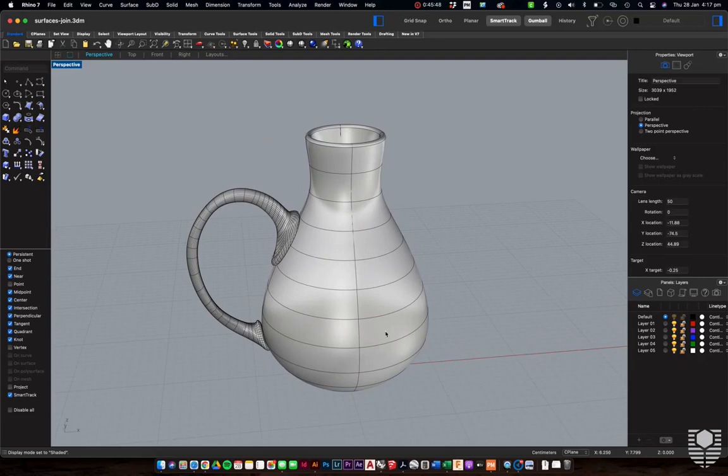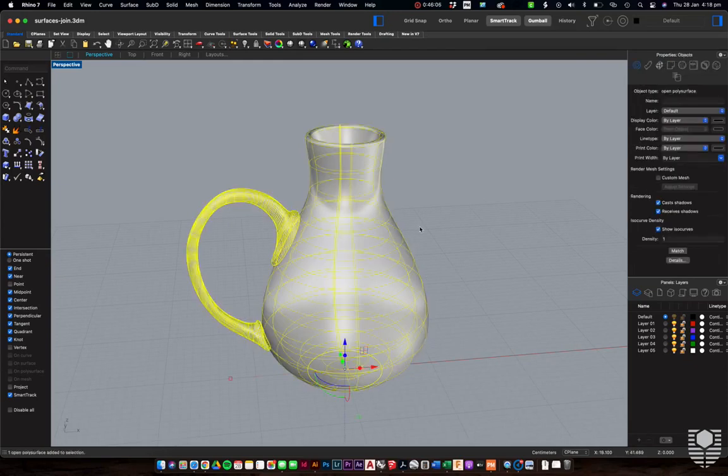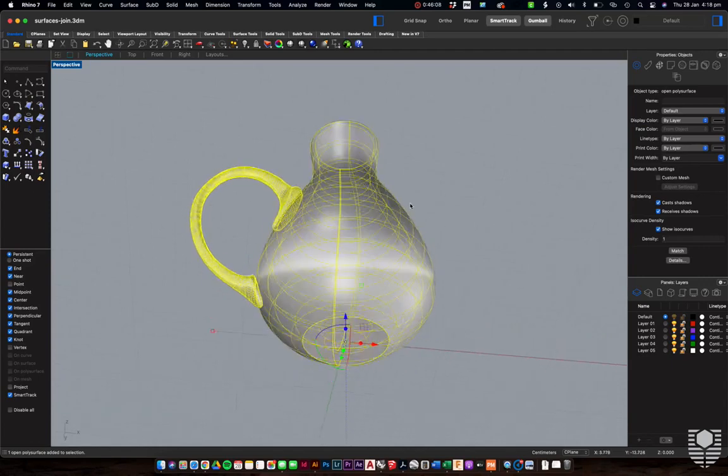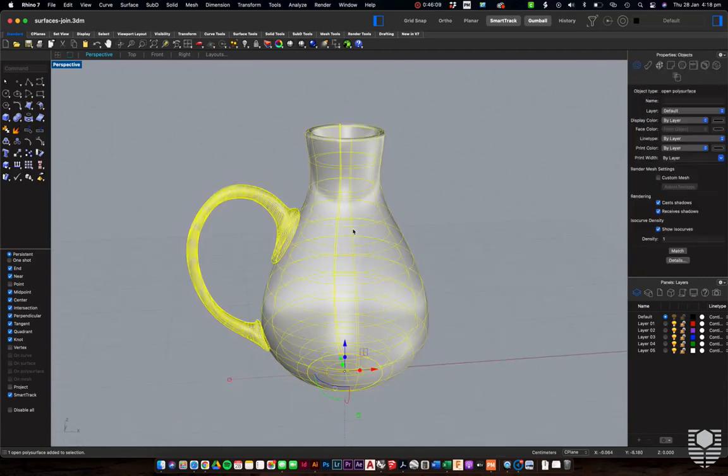But you know how to create these already. We've done all of this in today's video. This is a revolve surface. Remember, you create that sectional geometry, you revolve it around the Z-axis and you create this part of the jug. And then we have some lofts going on over here. And that gives us our two elements which have then been joined together. And we've got a base which has been filled in or capped in under this side here. So these geometries are currently joined together.